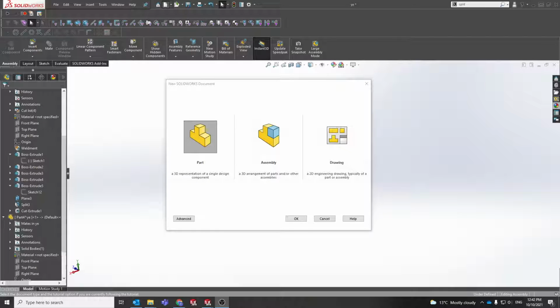In this video I'll be going over weldments. Think of having a standardized section, so let's say box tube or RHS or whatever it is, and using that with the weldments tool in SolidWorks to create a framework. But this video will be covering making custom sections, because the default library is kind of slim and doesn't have too much, so you'll need to add your own, or know where to put some if you find a library somewhere that has a bunch of files for it.